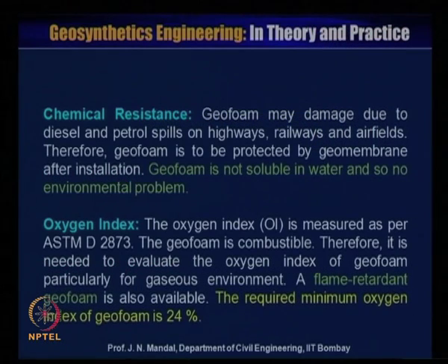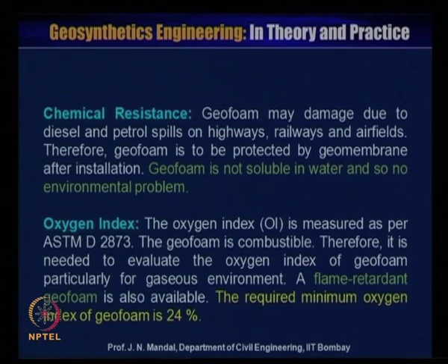Chemical resistance. Geofoam may be damaged due to diesel and petrol spills on highways, railways and airfields. Therefore, geofoam is to be protected by geomembrane after installation. Geofoam is not soluble in water, so there is no environmental problem. However, as we can observe, when it comes in contact with petrol or diesel, there will be no existence of the geofoam material.